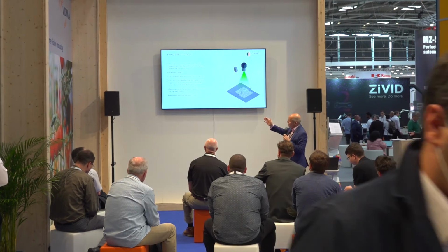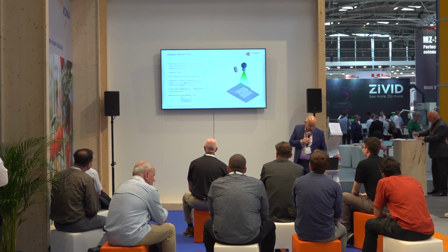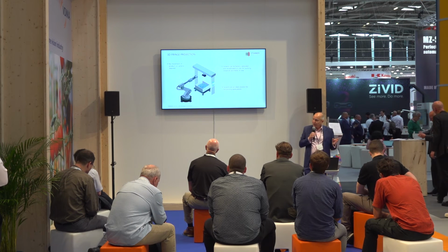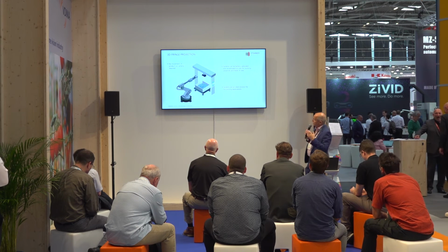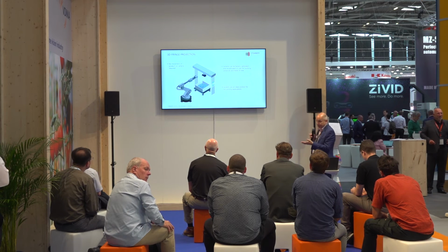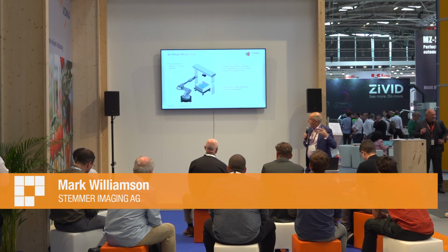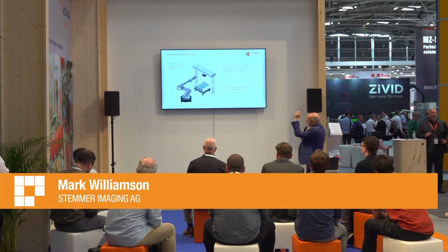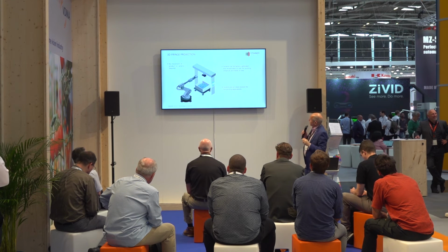Normally 12 to 16 images, which means the object has to be stationary for probably about half a second. So when you see these, you'll see them burst. So this is very good for things like bin picking. There's a lot of places, if you go to people like FANUC or LMI, they've got all these systems. You'll see it go lots of images to get the resolution.